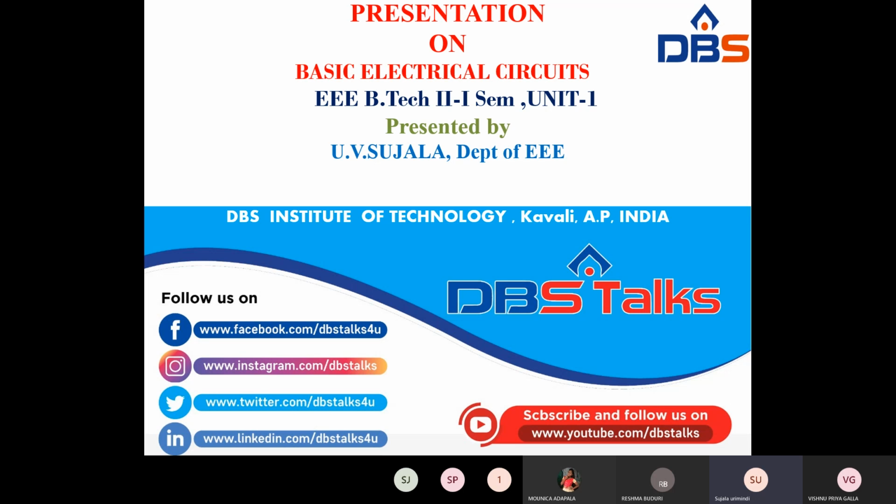When the sum of the voltages is equal to 0, how do you write the equation? Suppose there is a V1 voltage source here. I am saying the sum of the voltages is 0. The voltage is already there, so you simply put V1. How you assign the sign: minus to plus is the rise of potential. Negative to positive, minus to plus, there is a rise of potential, so put it as positive sign. So plus V1.